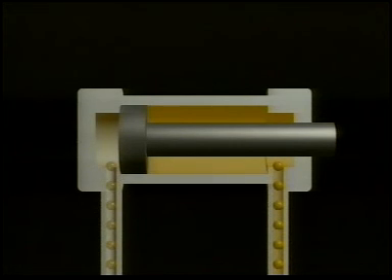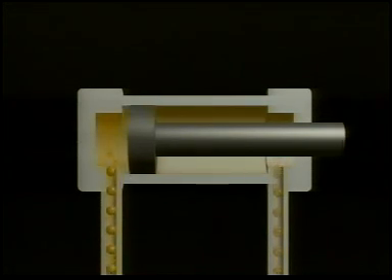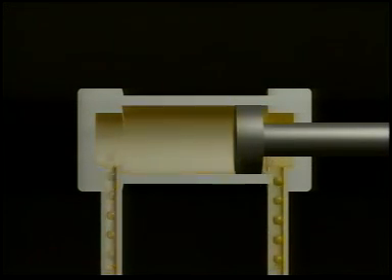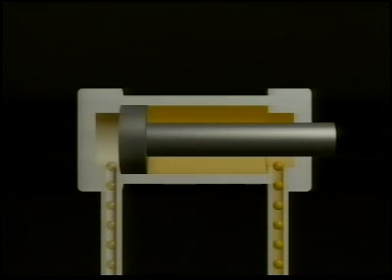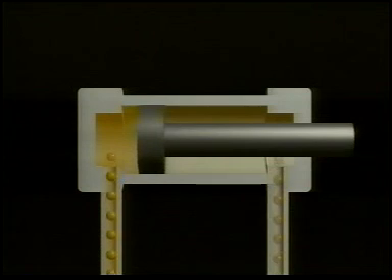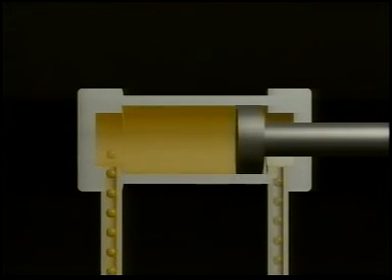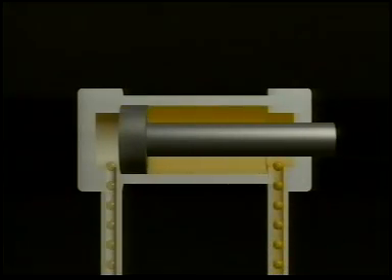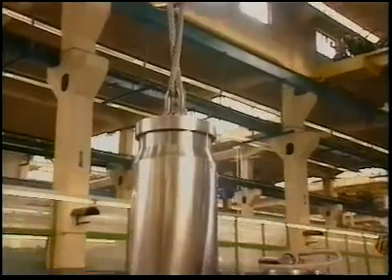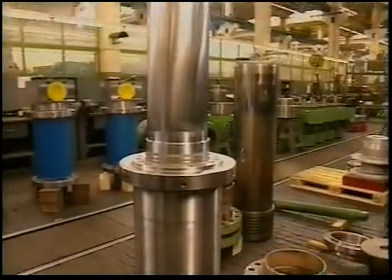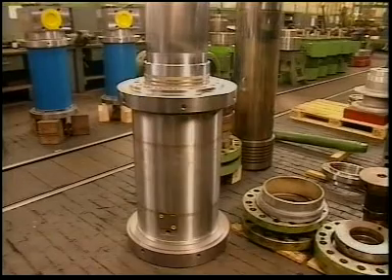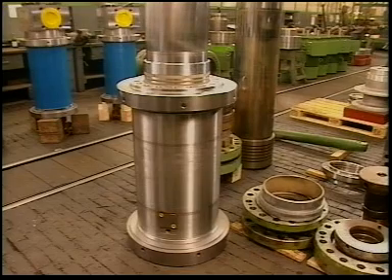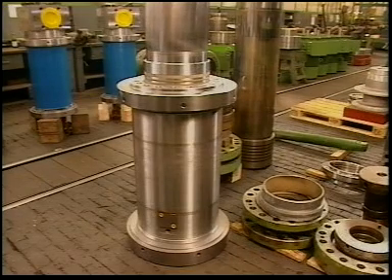The flow rate of the discharged oil is also twice as high because double the amount of oil must be discharged in the same time. This causes back pressure to develop. These laws must be taken into consideration when choosing hydraulic cylinders. In this special cylinder for a press, the piston rod has almost the same diameter as the piston, making the difference between the two piston surface areas extreme. This means that a slow flow rate is sufficient for relatively fast retraction of the piston.